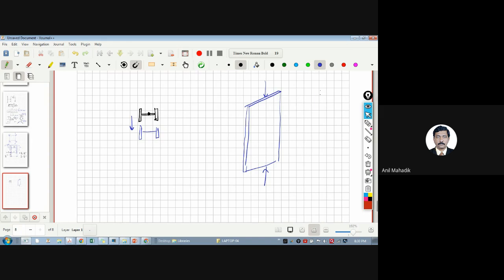So if I draw the cross section, ये मेरा cross section है. So there are two elevations. One is this elevation and second is this elevation, right? And there is a compressive force. So definitely it will try to buckle in this direction, not in this direction. Yes or no? It will not buckle about the major axis. It will buckle like this. Are you getting this, what I'm telling?